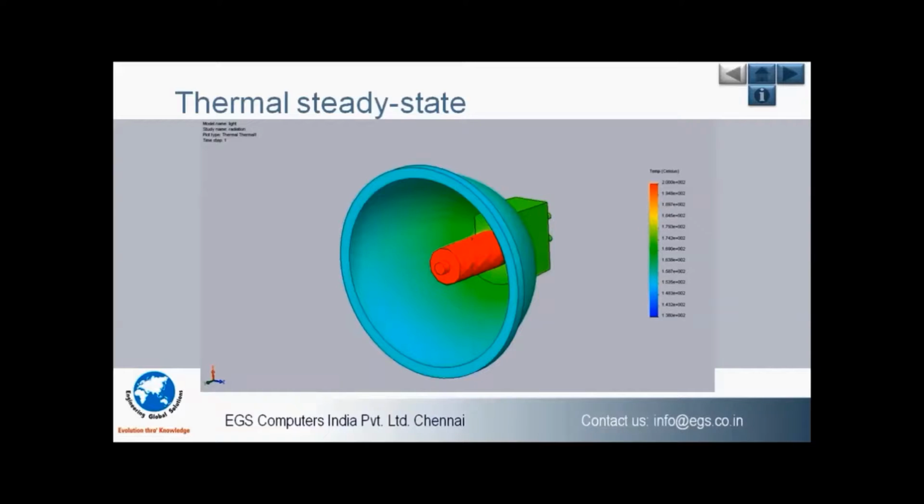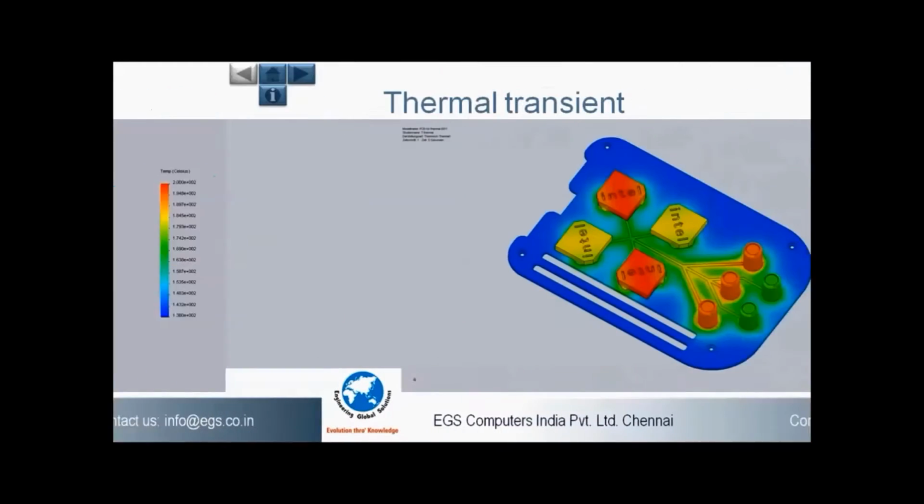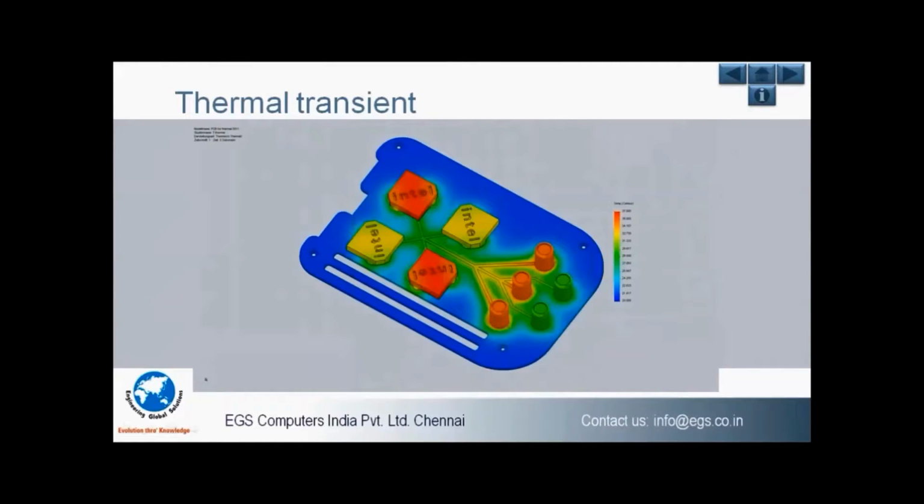For those of you who are from the automotive systems, we must consider the heat-related defects on the products also. This we can overcome using the thermal analysis, and SolidWorks simulation can do a coupled analysis for finding the thermal stress by directly linking the static and the thermal studies. The thermal analysis can also be done using a steady state condition or a transient condition.